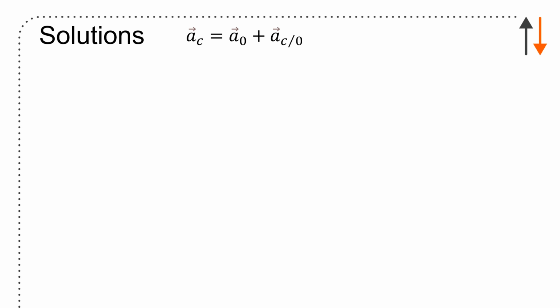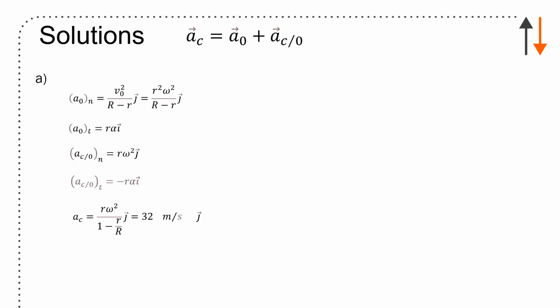So we're interested only in the acceleration of point C, which is the acceleration of O plus the acceleration of C relative to O. If we do that for the first half, remember that that is on the inner side, and the curvature is like this, and point O is over here, C is over here. C is a point of no slip.